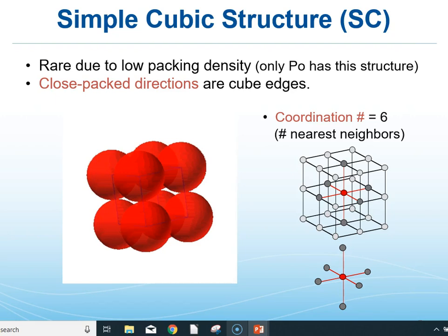Okay, getting into metallic type of crystal structures. There are basically four. Simple cubic, which is only one material that we know has it, at least as a single element, and then the big three, body and face-centered cubic, and hexagonal. So simple cubic structures, even though they're only represented by polonium and not very useful for an engineering sense, do give you a really simple way to visualize a crystal structure. It is literally a cubic system, meaning that every edge is the same length and they are all at 90 degrees to one another. There is an atom on every corner of the cube.